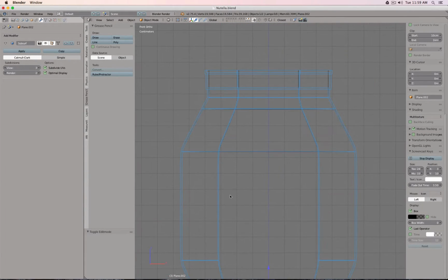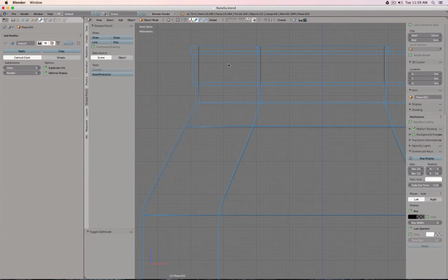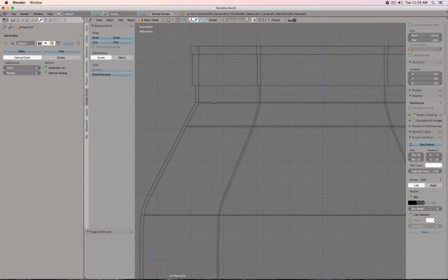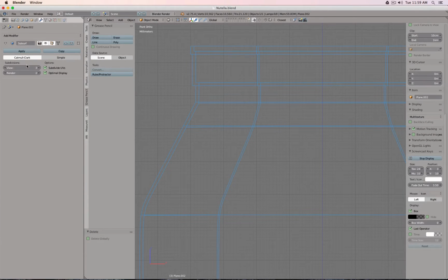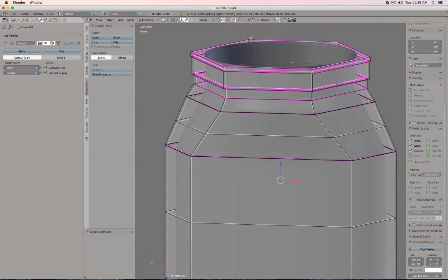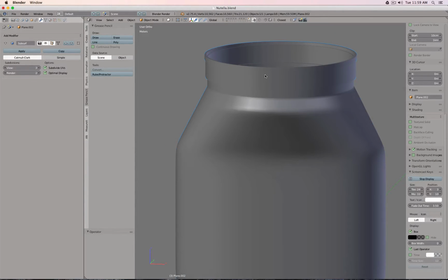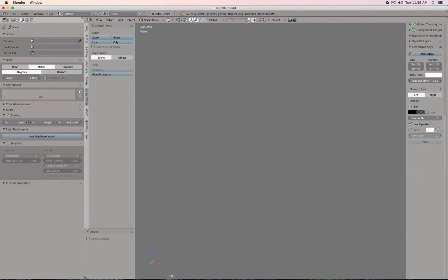Yeah, they actually match up. So you could also utilize that command because it gives you the same result. Very often, because I'm so used to using the solidify modifier, I simply add it, set it up, and then I do all the other commands by hand. Okay, so this can go.